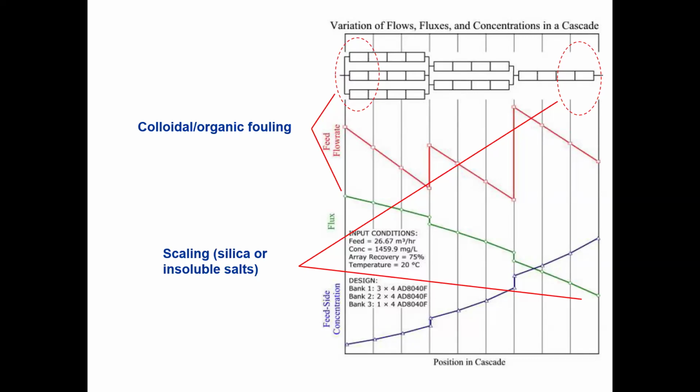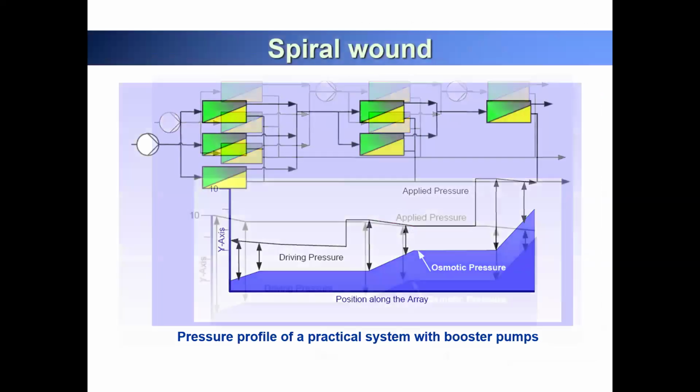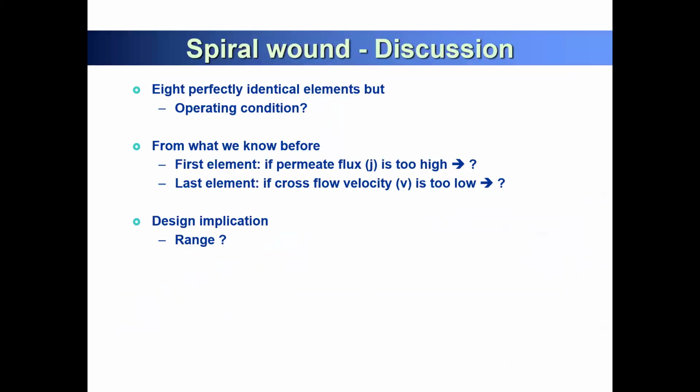So that's how they create the problem of overall membrane fouling and change the water flux. That's a good question, because the problem is that your software cannot calculate this, since it depends on your water quality, your pretreatment, the temperature, and the recovery. So you cannot calculate it perfectly, but at least we can consider a similar pattern in our design for this fouling impact.